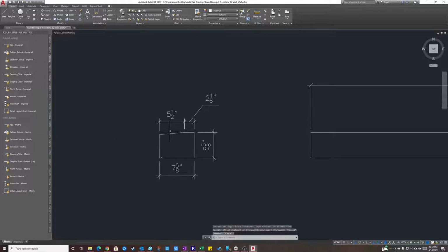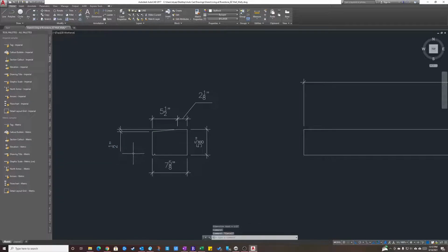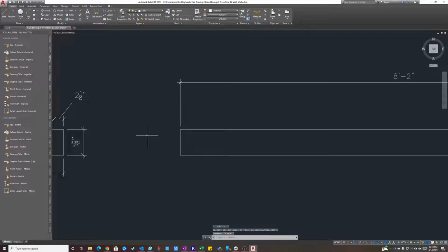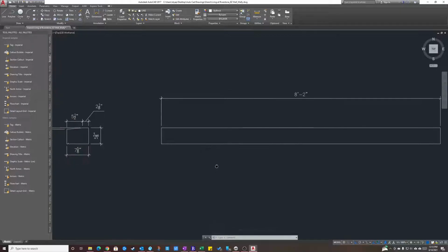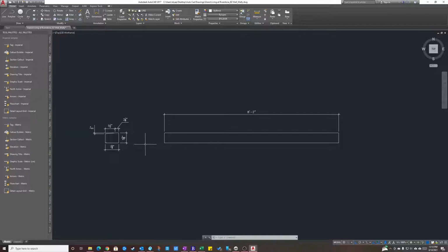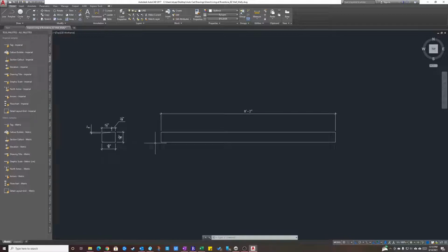So this offset here, it's a 1/2 inch slope, right? So 1/2 inch, so we'll measure it again. So yeah, it's a 1/2 inch slope. And we should have put that dimension on there previously, but now it's on there for better understanding. So we're not seeing that slope right now. What we need to do is we need to draw it. So the logical way to do that would be to use our offset tool.